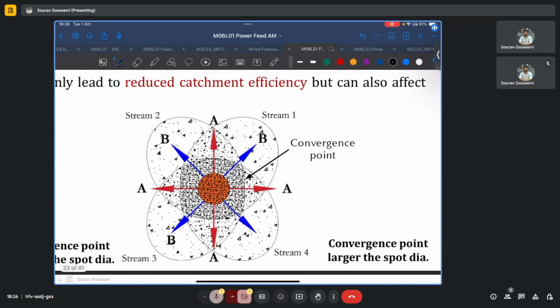Whereas in the second case, where the overlap region is larger than your laser spot size, irrespective of the direction you might want to move in, whether it be along direction A, some intermediate direction B, or along the horizontal, we see that because the overlap region of the powder streams is so large, omnidirectionality is maintained, and thus we can expect reasonably isotropic properties irrespective of the direction along which we are scanning.